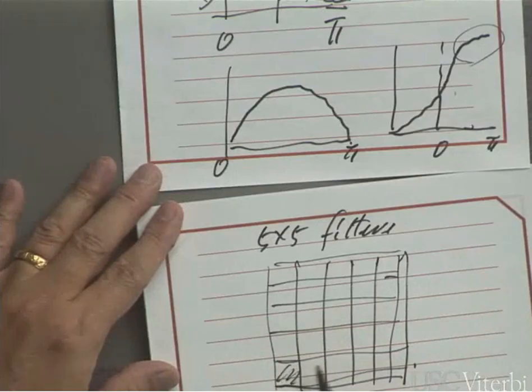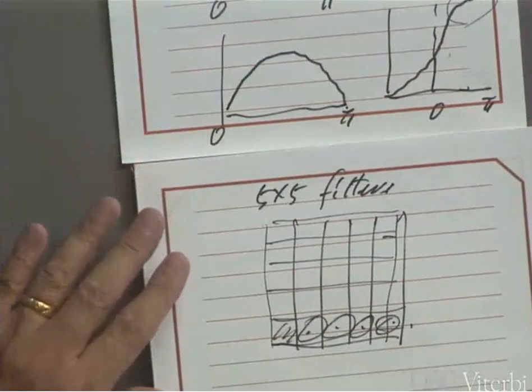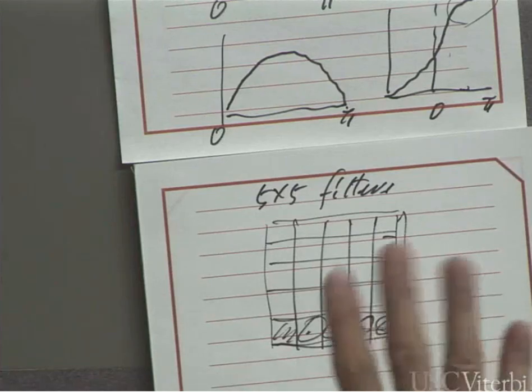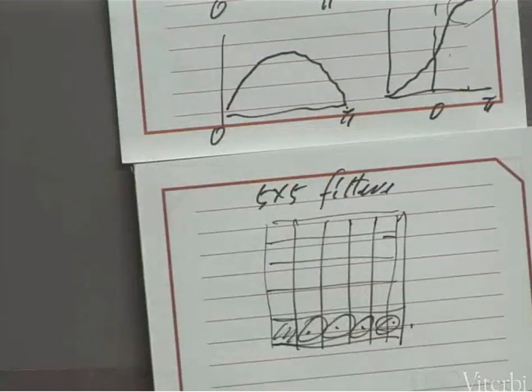Okay, so each band has a certain band for each. You do a spatial domain operation, but in the frequency domain, it's like you pass a certain frequency band and suppress other frequency bands. So you only focus on that band pass, the particular band signal. And then usually you compute the energy in that signal, in that band. So the energy in that band becomes the feature. Is that clear?